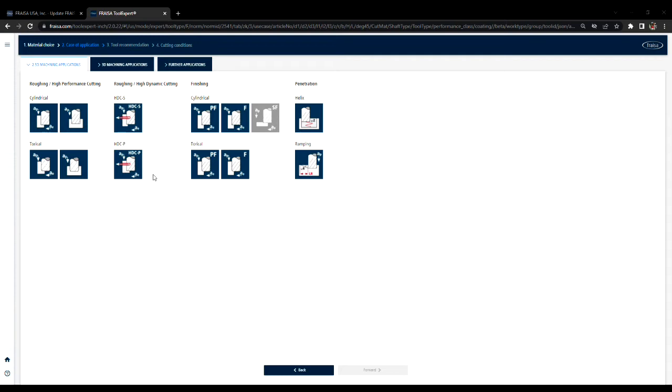These are split into two different categories, the HDC-S category and the HDC-P category. The S, or the speed settings, are meant for machines that like lighter radial cuts and higher feed rates, where the P, or performance settings, are meant more for machines that prefer a heavier radial step over and slower feed rates. Regardless of which setting you select, your material removal rate will remain the same.